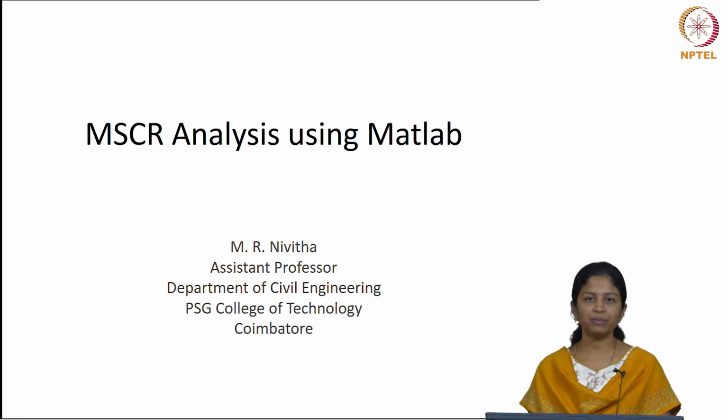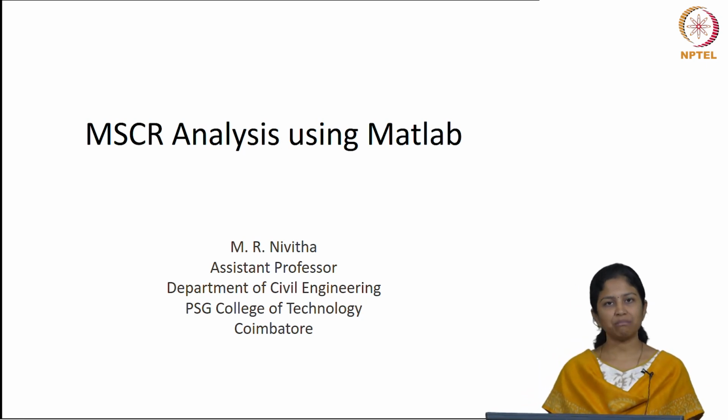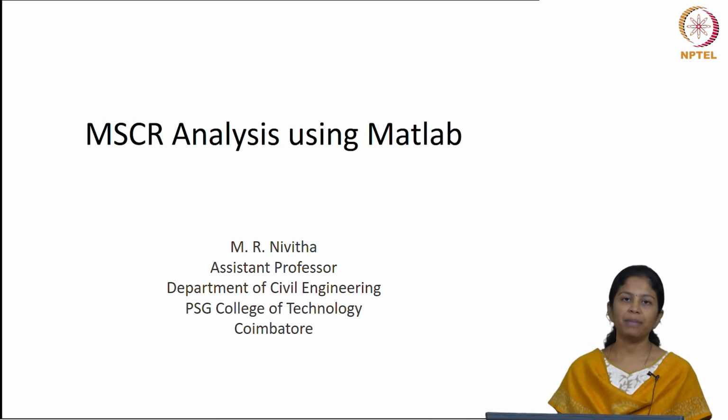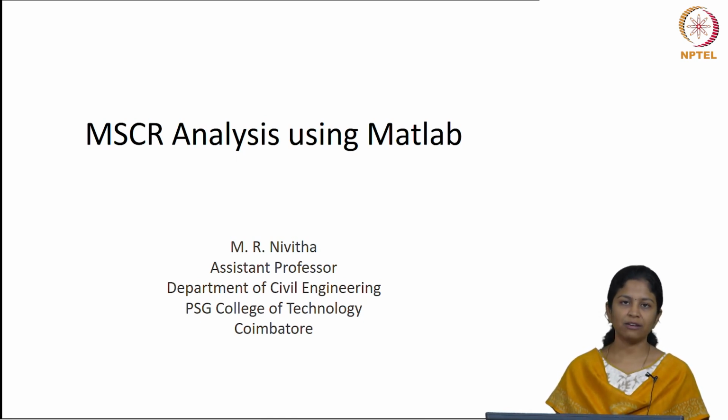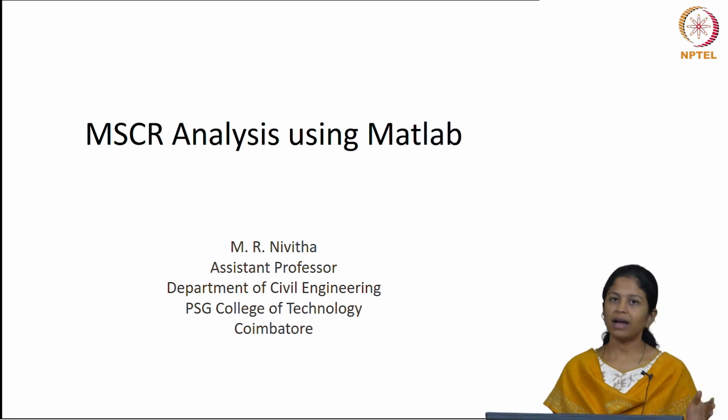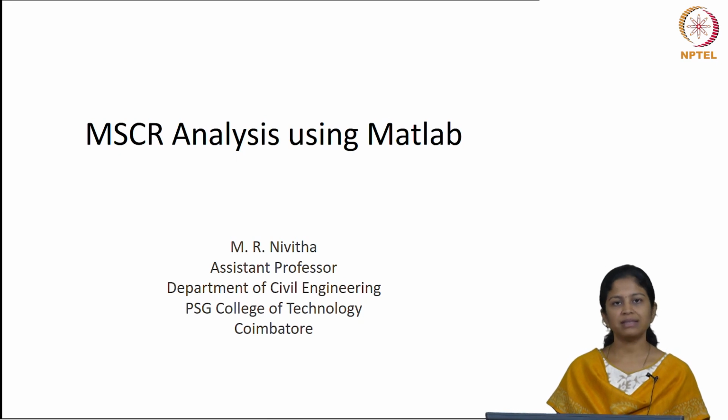So, in this lecture we will see how to import MSCR data into Matlab and how to calculate the parameters which are specified in ASTM D7405. They ask us to calculate percentage recovery at two different stress levels, non-recoverable creep compliance at again two different stress levels, and the percentage recovery difference between the two stress levels and the non-recoverable creep compliance difference between the two stress levels.